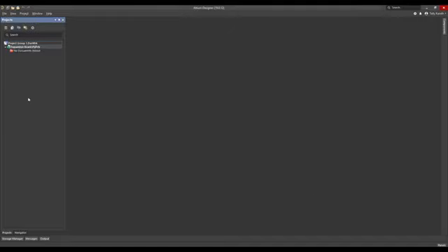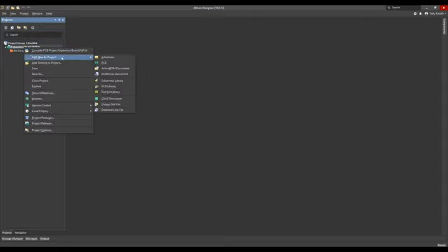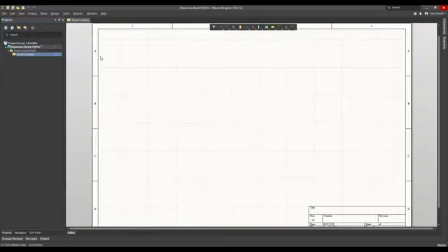This panel is a Projects panel. Altium uses panels to provide access to information and tools. These panels are specific to the current document that is open and active. Now in this project we can add schematics by right-clicking on the project file name and selecting Add New to Project, then select Schematic. This will add a new blank schematic to this project with the default name.